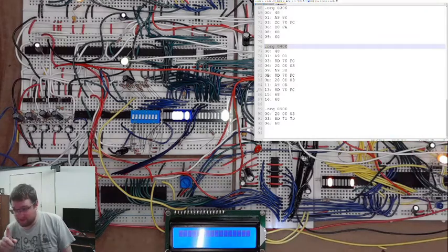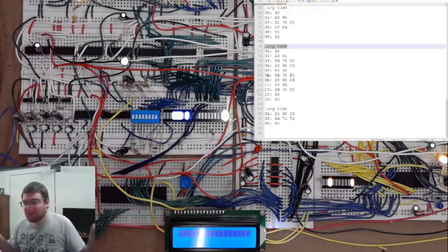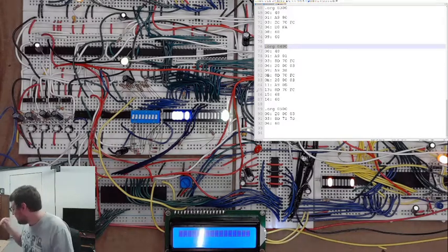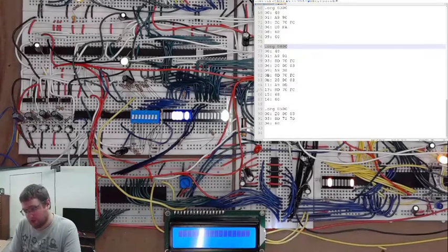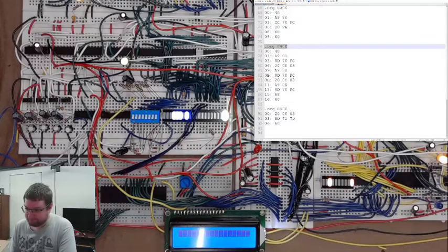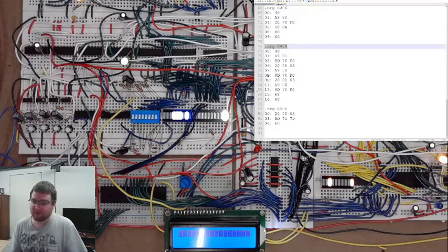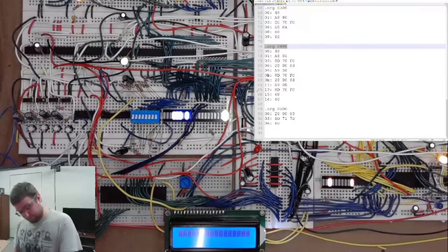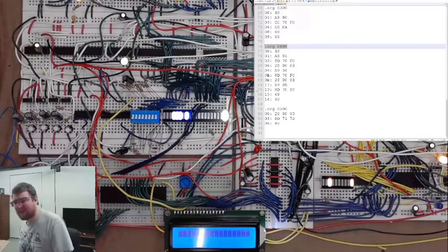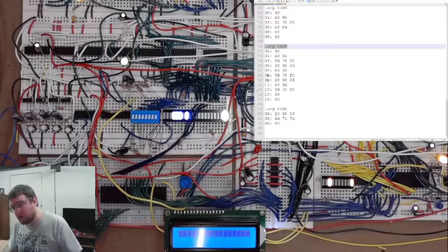Now there's a trick with the 816 you can do. I don't know why I'm explaining all this right now. I gotta explain it. I'm excited about this, okay? There's a trick where it actually has an instruction to move a block of memory to another block. This is extremely fast. And because every clock cycle it moves the next byte. Or maybe it's every 2. It takes 2 clock cycles to move memory, which is better than like the 5 or 6 clock cycles you usually have to use. So copying memory is pretty fast.